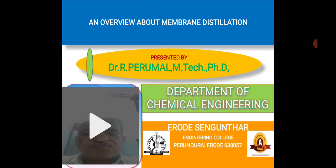So membrane distillation is a most useful technology in modern separation processes, which employs a hydrophobic membrane and operates as a thermal separation process. Like distillation, here also a temperature difference is employed. The driving force is vapor pressure difference. The hydrophobic membrane selectively allows only vapor to pass through the pores of its membrane.